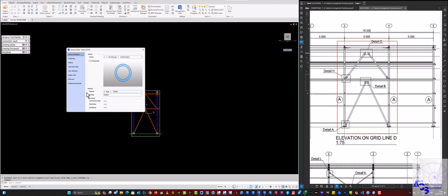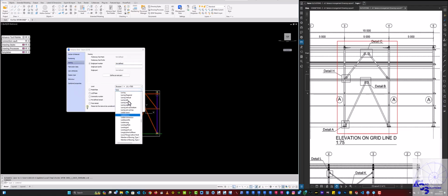All right, remember guys, you also have to add material and coating, painted or galvanized, depending on what the project spec says. Positioning is in the middle. Naming, there is none there, so I am going to just say this is a beam. Then for this level, we don't need to change anything, we might just leave it as it is. So there's nothing to change from there.